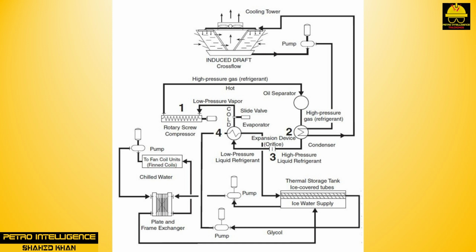Because heat is transferred from high-temperature areas to low-temperature areas, whenever it is necessary to cool a substance below ambient temperatures, it is necessary to artificially create a lower temperature first. To lower temperatures, process plants use fluids that boil at very low temperatures such as propylene, ethylene, or ammonia, that is, the same principle as the freon in your refrigerator, car, and house air conditioner.